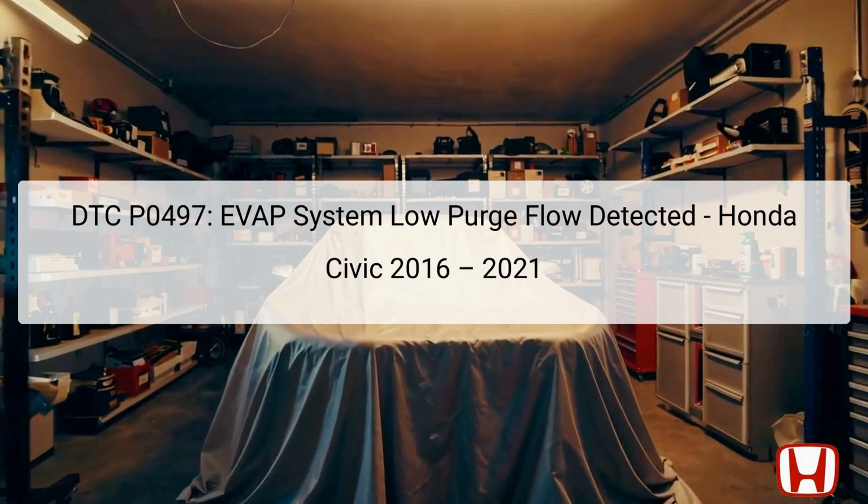The components involved in this system include the EVAP canister purge valve, the fuel tank pressure sensor, FTP, and the related vacuum lines. Each of these components plays a specific role in ensuring that fuel vapors are properly evacuated and that optimal performance is maintained. The EVAP system location varies, but the purge valve and canister are typically found in the engine compartment, near the intake manifold and the fuel tank.